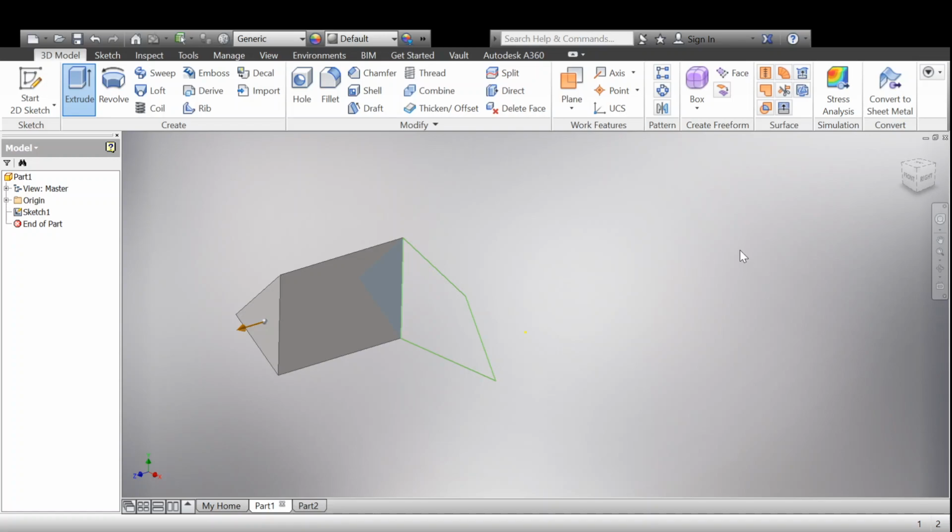First, how far you want it to go. You can choose distance as your option, and you could sit here and change the length by pulling this arrow out or moving it inward. Or you can directly type the dimension of the extrusion you want right here. Now, in addition to that, there's some other interesting ones. This goes backward instead of forward or in the opposite direction.